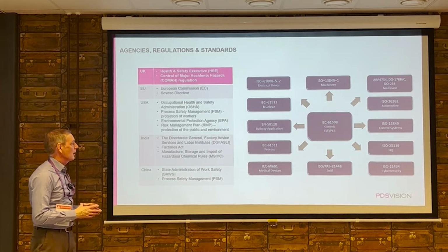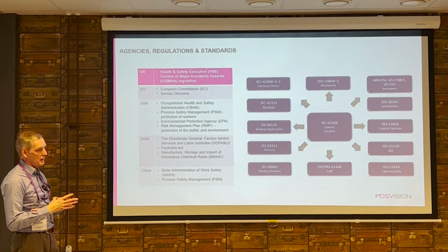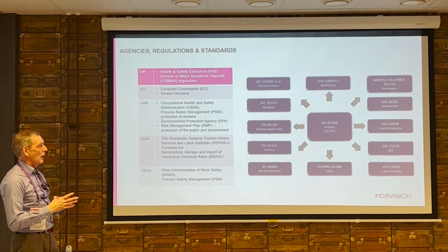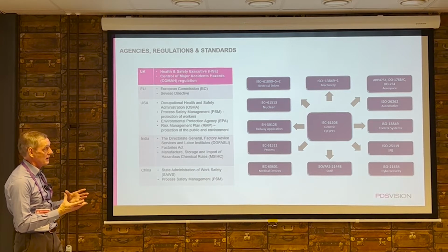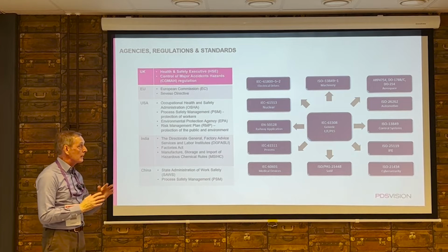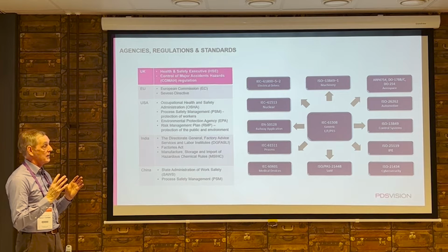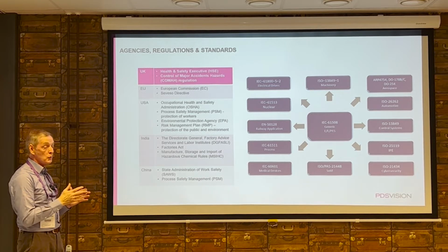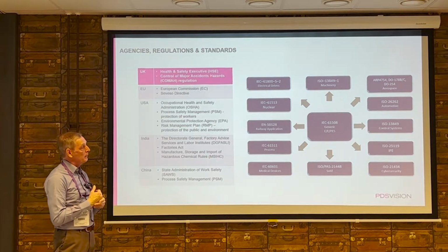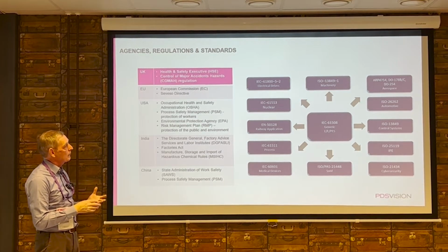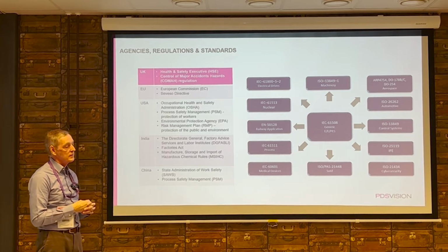So in the field of functional safety, most of this is driven by the industry that you're working in. The father of all functional safety standards is the IEC 61508, which is the one in the middle. And from that, various industries have taken these standards from IEC 61508 and made them much more specific to the industry that people are in. I'll give you a couple of examples a bit later on: ISO 13849 for general machinery, and also ISO 26262, which is for the automotive sector.